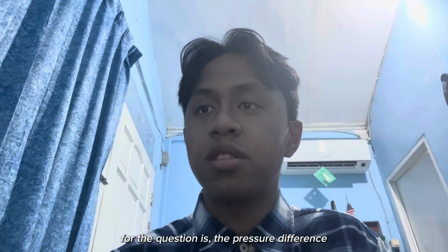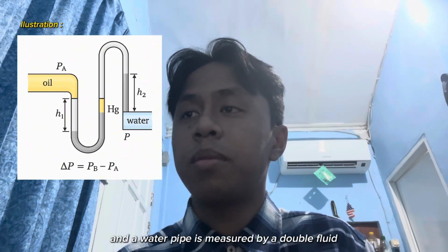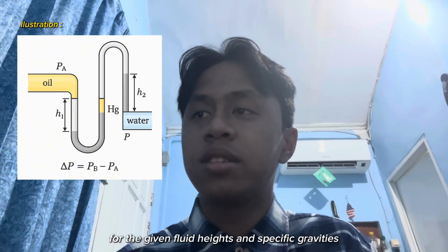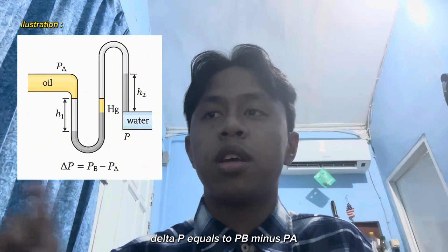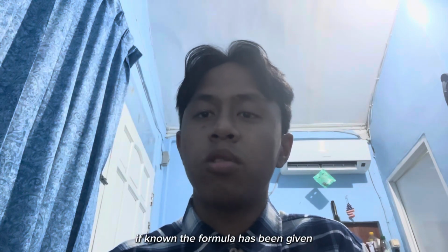For question number 4, the pressure difference between an oil pipe and a water pipe is measured by a double fluid manometer as shown in the figure below. For the given fluid heights and specific gravities, calculate the pressure difference delta P equals PB minus PA. If known, the formula has been given.